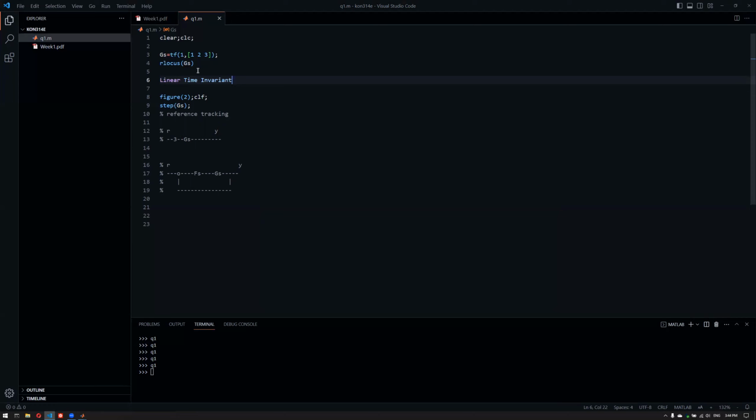And it is linear in the sense that if I have input 1 and output 1/3, I can just multiply everything with 3 and it will hold. So it means that if I have input 1 and output 1/3, if I input 3, I will get output 1. So therefore, this is called linear. Therefore, I can just find out what the steady state value of the given transfer function is, and then calculate it and take the inverse as a controller in the open loop control strategy.